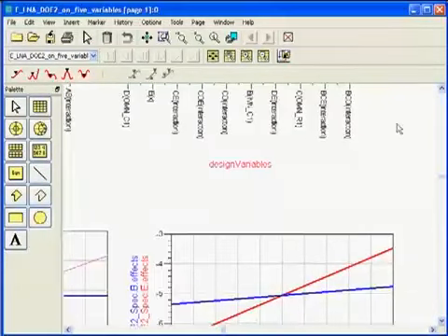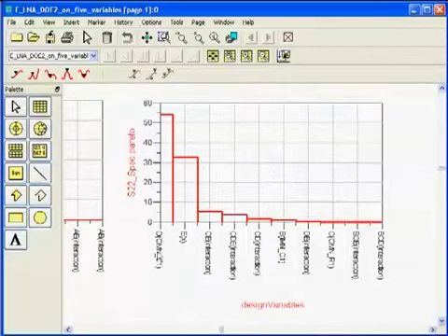Now if we look at the S22, notice the output matching network capacitor C1 is causing about 55% of the variation in S22. And notice the width of the line again is causing about 32% of the variation. And we have some interactions now between elements. Notice about 6% of the variation in S22 is caused by interactions between the width of the line and the resistor R1. There is some interaction between that resistor R1 and the width of the lines.